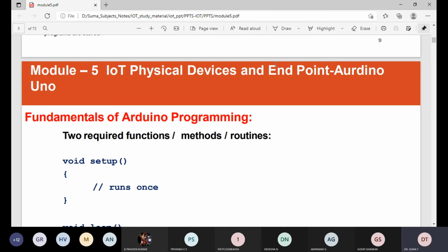In order to keep our circuit organized, the breadboard allows you to connect the components together by plugging them into the little holes. The key is to understand how these holes are connected. The holes in a column, when oriented as shown in the pictures, are connected together. So to connect components, you need to plug the leads you want connected into the same column. Note that the columns are not connected across the trench in the center of the board.